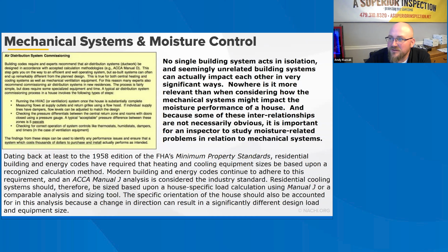An ideal return air system provides unrestricted pathways for return air to travel to return grills. To achieve this type of return system, the inspector should see multiple returns with the ducts formed from actual duct materials and not building cavities, or jumper ducts or transfer grills to provide return air passageways from rooms that can be isolated when interior doors are closed, which is moderately effective and moderately expensive, but may carry privacy objections.